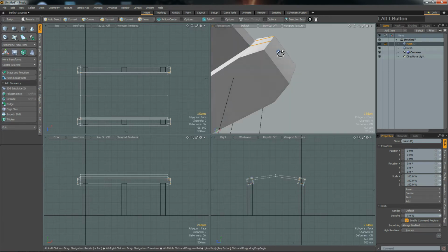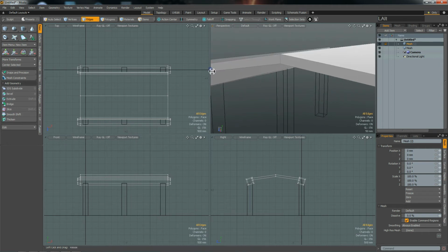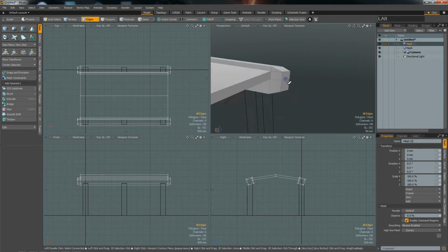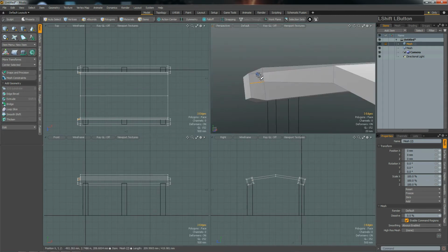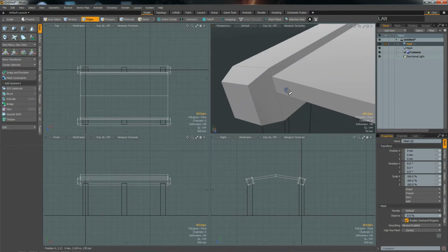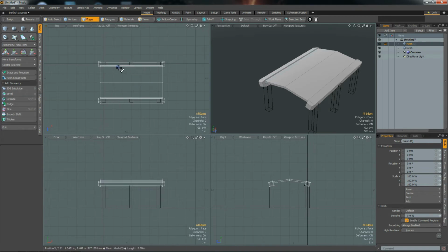Those meshes here, since they are on the same plane, I can safely delete them. The same here and on the other side. Now here it's okay to do it like this because we only have 4 things to delete. But let's say we have something that's more complicated and we spend a lot of time just taking care of one part of this mesh. What we could also do, if it happens to be symmetrical like this one, is cutting it up, deleting everything except for a quarter, and when we finalize this part, then mirror it and put it back together.